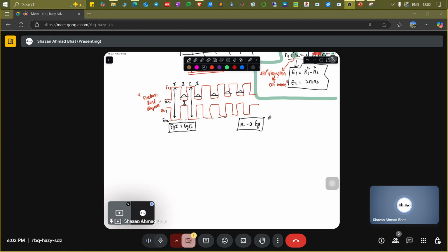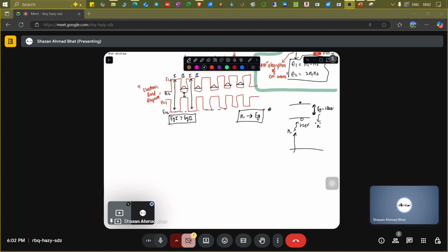That is why certain electromagnetic waves are absorbed inside the semiconductor. Let's say you have a semiconductor with an energy gap of 1.2 electron volt. If you have an incoming photon of 1.2 electron volt, it will get absorbed and will create an electron hole pair in the system. That is governed by this Eg, and Eg in turn controls the refractive index. So they have an inverse relation. If you see how the refractive index behaves with the Eg, it goes as inverse. That means as the band gap increases, the refractive index reduces.